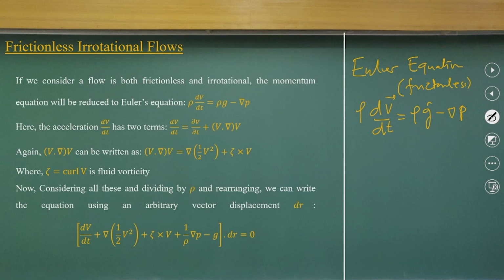We can look at this component as I wrote it earlier. This component, which is the acceleration component, I can split into local accelerations and convective accelerations. Just look at the vector relationship. So you have the convective acceleration component, and that is what is here.